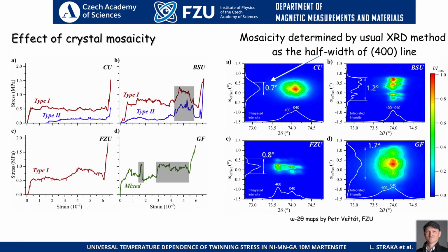And we also measured crystal mosaicity, which I would like to introduce in this small figure: no crystal is truly perfect. It consists of mosaic blocks which are a little bit misoriented, and you can see this misorientation using X-ray diffraction, for example, in omega scans, where you typically obtain several peaks corresponding to these individual mosaic blocks.